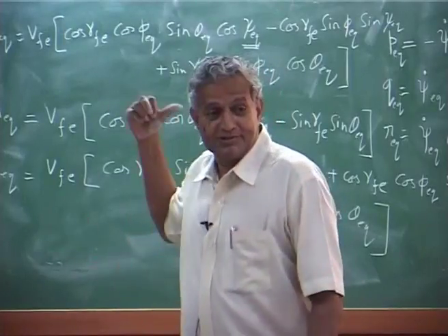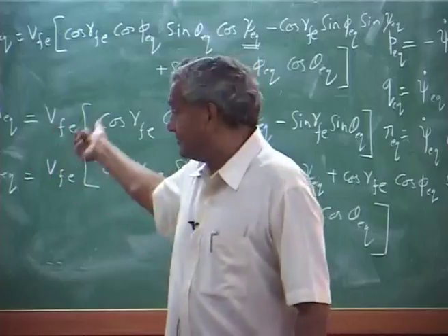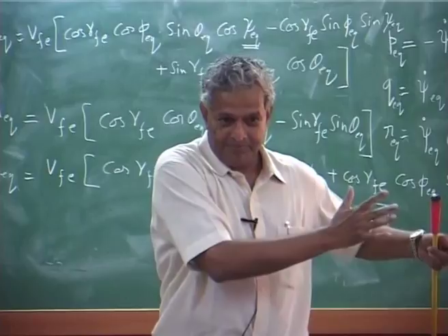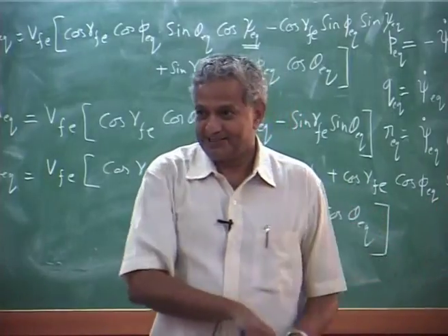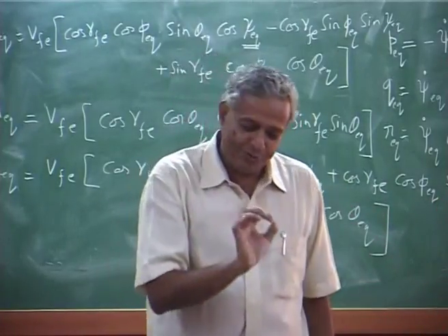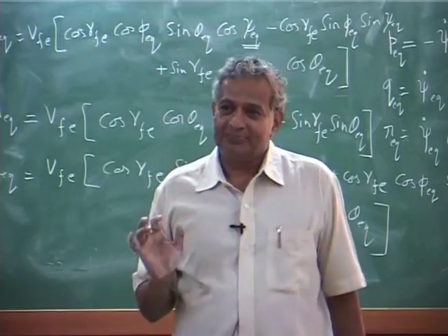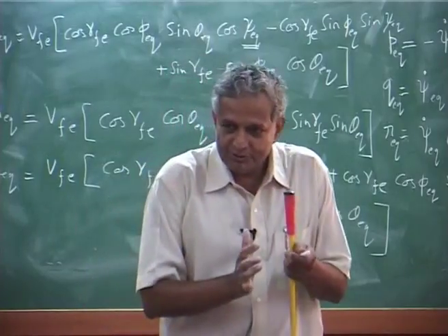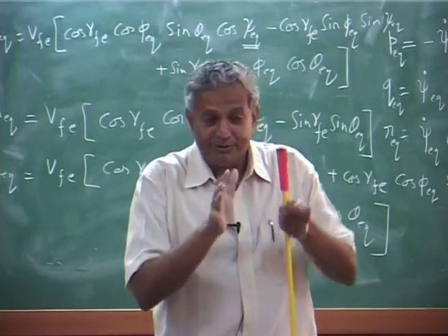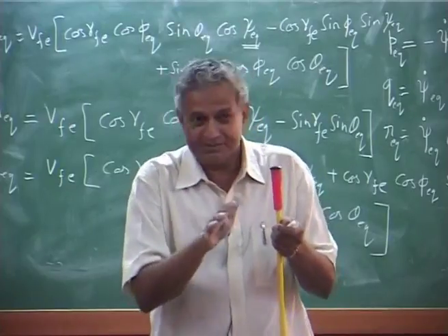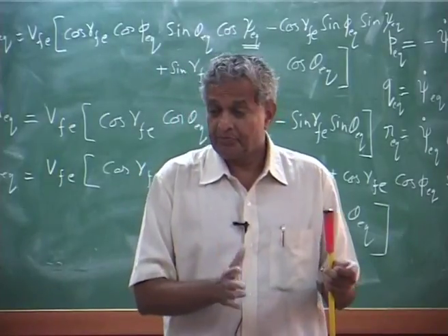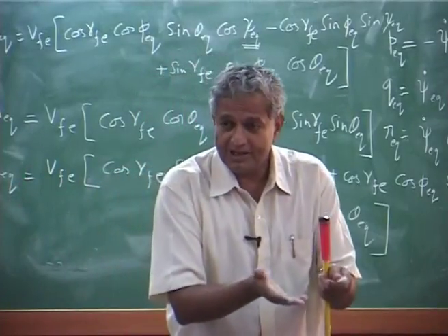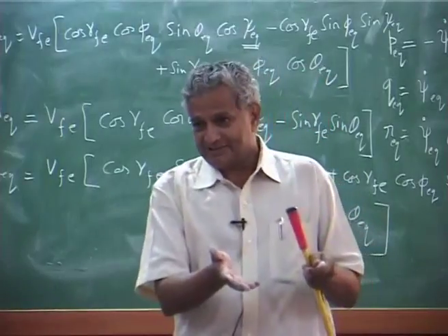That one you can go and solve my linearized delta u, delta v, delta w, that equation, that is the perturbation only. Okay. But that will give you only at the instant what is happening, it will not tell you over a long time, because however you would have done the equilibrium about a hovering condition and a perturbation about the hovering condition, but you go to forward flight at some other speed, then you will have an equilibrium and a perturbation for that.